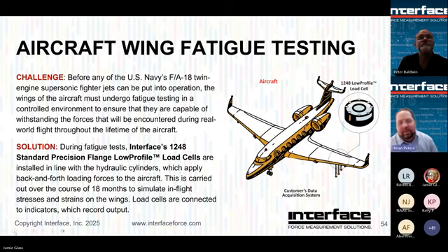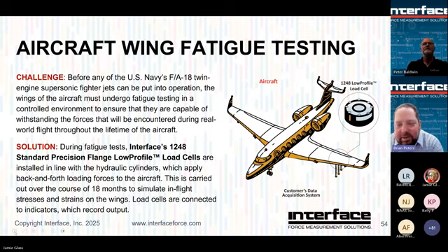All right, pretty basic fatigue test example here. This is the luxury edition of an F18 apparently, but no, very, very common application for interface load cells, full-scale fatigue testing. 1248 is highlighted here just as an example, again, to be able to integrate directly with the actuators that were used. Fatigue-rated flange model, good for 100 million full reverse cycles.